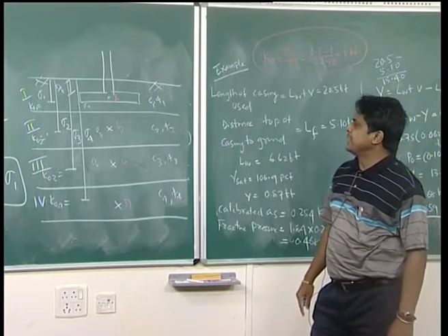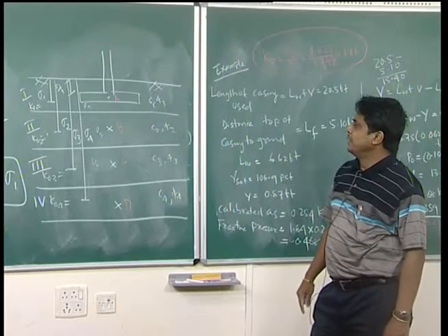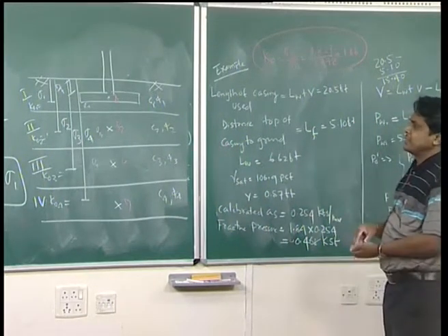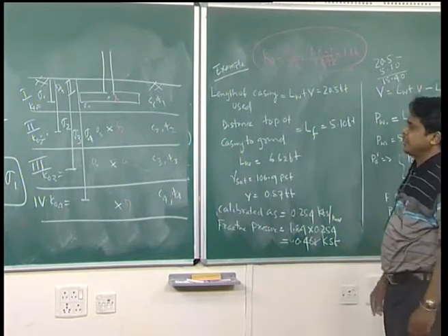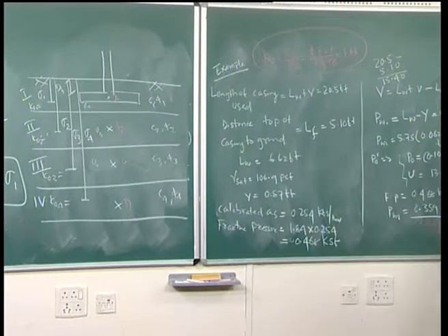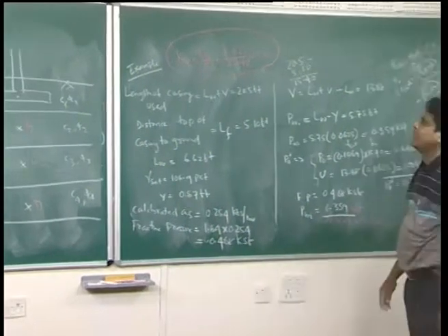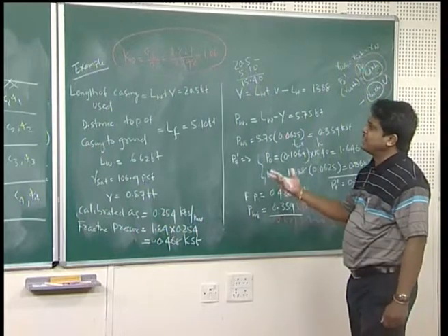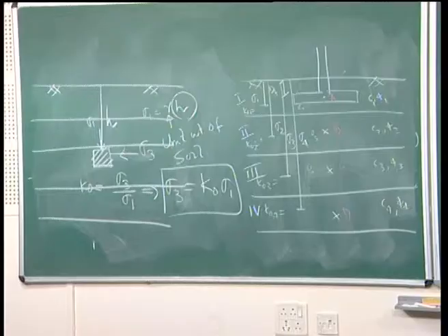So this is basically the requirement for field explorations, to know the engineering properties. It has the advantage that you get the K0 value in the in situ conditions, without disturbing the soil sample inside the ground. Then once you get the K0 value, the rest of the problem will be solved.